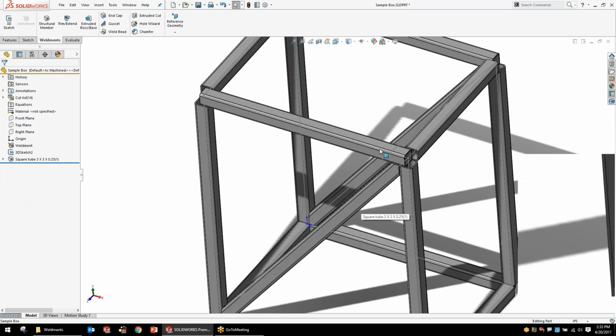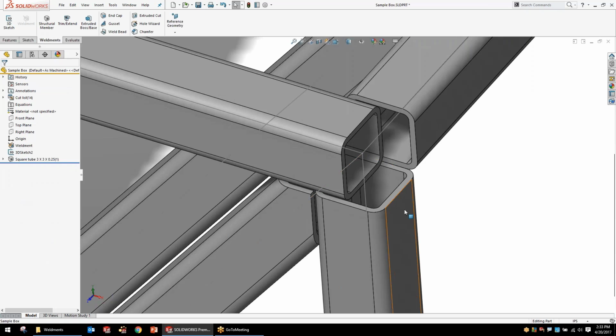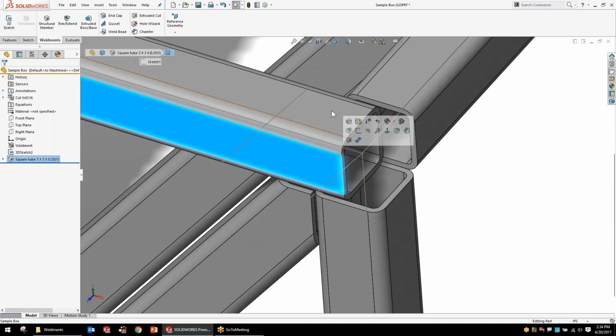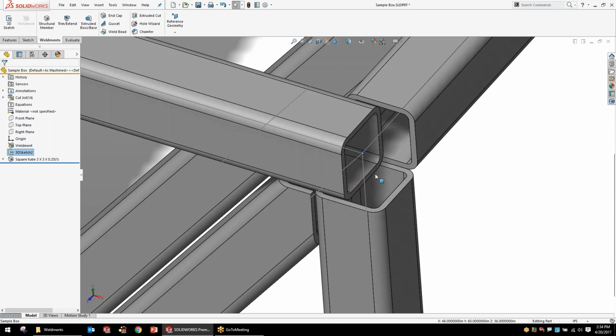You'll notice that there is one little problem here: it does not extrude all the way to the end. That's because right now the cross-section profile of our tube is extruded along the length of the tube, but this tube extends more vertically than the corner does. It does this by the point along the cross-section profile that it grabs, which is the origin by default, but we could locate it to a different one of the points in the cross-section profile. But what this ends up with is sometimes you don't get the corners to extend all the way out.